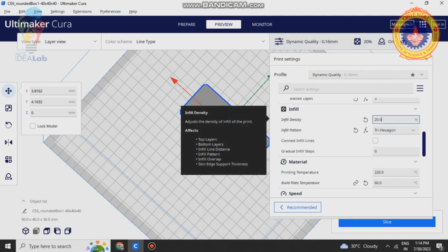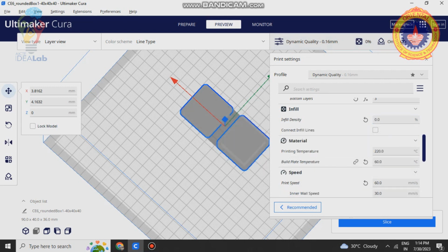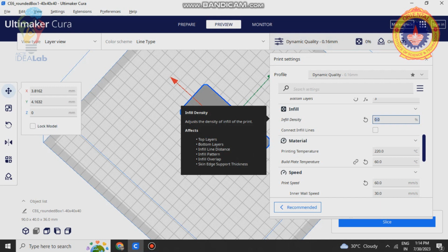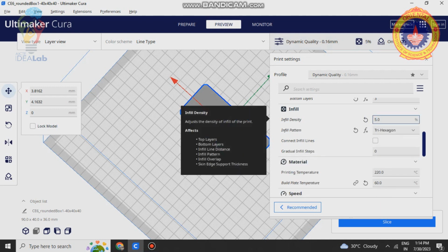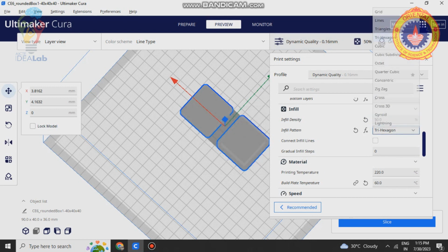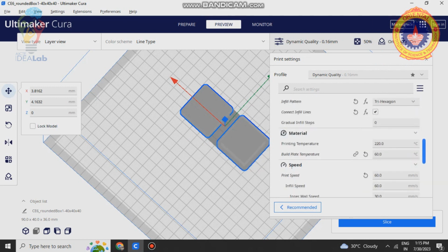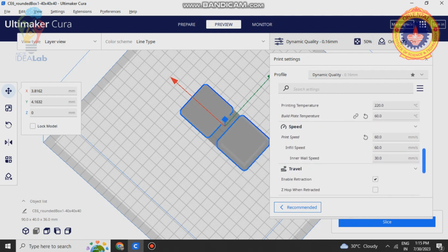So infill can look cool, add strength, save money, all depends on the print. Different types of patterns can work well on different infill densities with different kinds of strength. Typically with prints of 0 to 15 infill density, we use the lightning, lines or zigzag infill patterns as they are the best because they give the fastest prints. Material temperatures are also normally set by the machine. However, we can change the temperatures here as well.